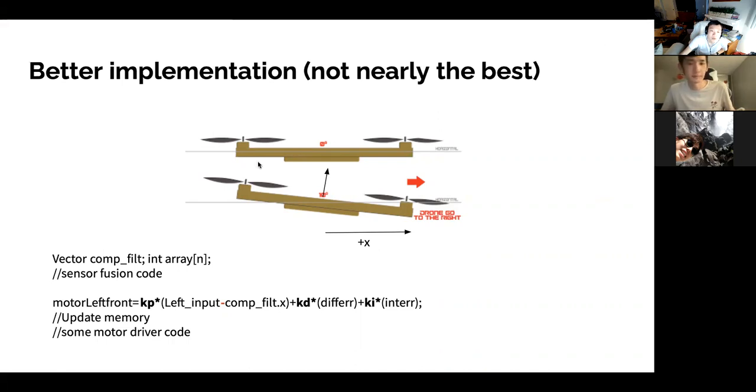One thing about your array of values, like a buffer, to an extent, like your memory, is that, as Eric mentioned earlier, finding a balance for the size of that buffer is going to be pretty important, because our MCU is fast, but it's also not insanely fast. So you'll have to keep in mind that all of your derivative and integral calculations utilize all the values in that buffer. I have another slide on that, so we can talk about that a bit.